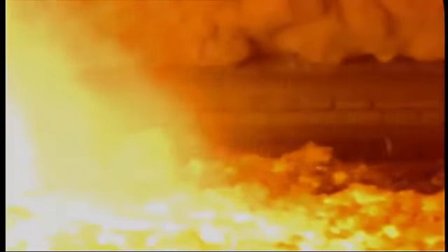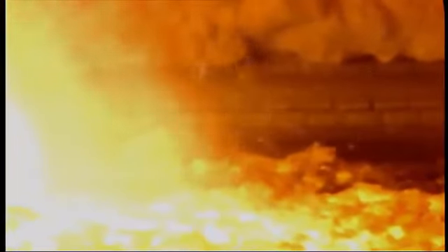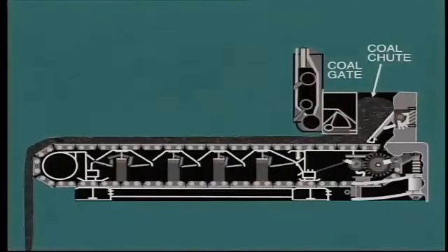Several inherent problems exist with this type of burning equipment. One is the potential for combustion to be incomplete and consequent discharge of combustible material into the ash pit and then to waste. Another potential problem is the failure of the coal bed to ignite, so that the whole bed of green coal may be discharged into the ash pit, while the boiler rapidly loses pressure.